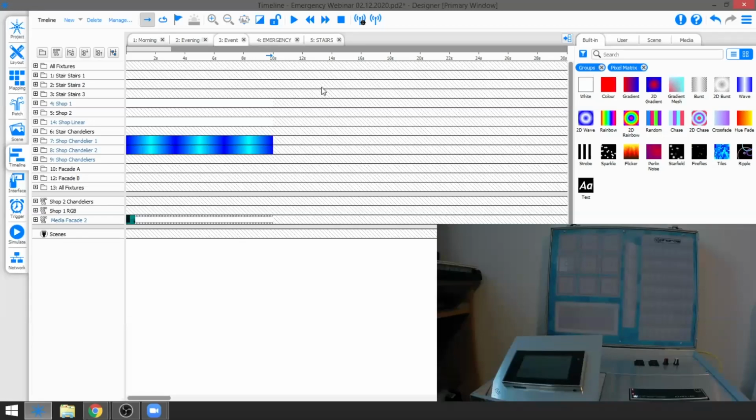Also, I should notice that timelines and lighting scenes within Pharos never release unless they are told to. So effectively what you create is a stack of timelines. If timeline 1 is selected, that goes to the top of the stack, and if timeline 2 is selected, that then goes to the top of the stack, and timeline 1 will just slot in underneath it. That is obviously with the exception of priorities, which I've talked about already, which mitigate that latest takes precedence rule.